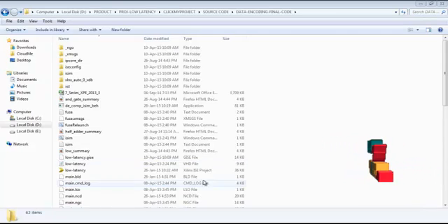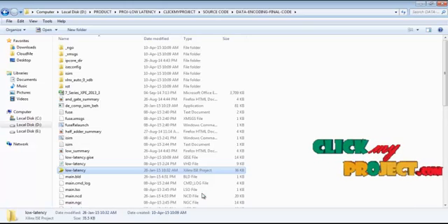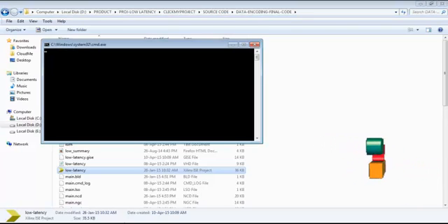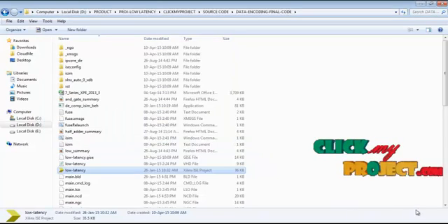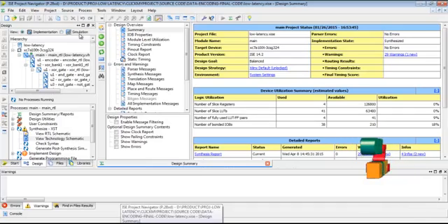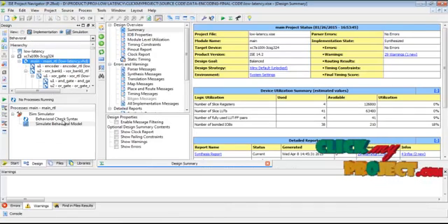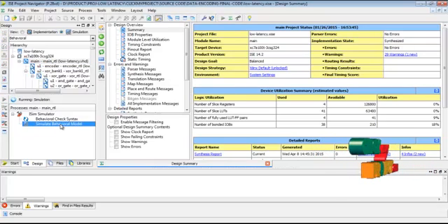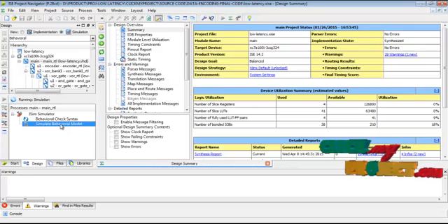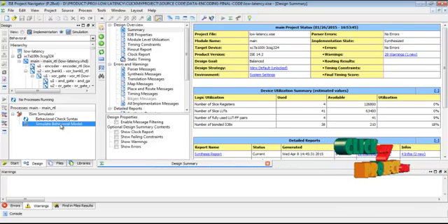Then open the Xilinx ISE project for our data encoding architecture. Then select the simulation process and select the main RTL functions. Then double click simulate behavioral model. This behavioral model creates the iSim project navigator. This navigator is mainly used for the simulation of the data encoding process. Then the data encoding process applies the input data bits, encodes the output data, and creates the decoded output data bits for the same data encoding bits.